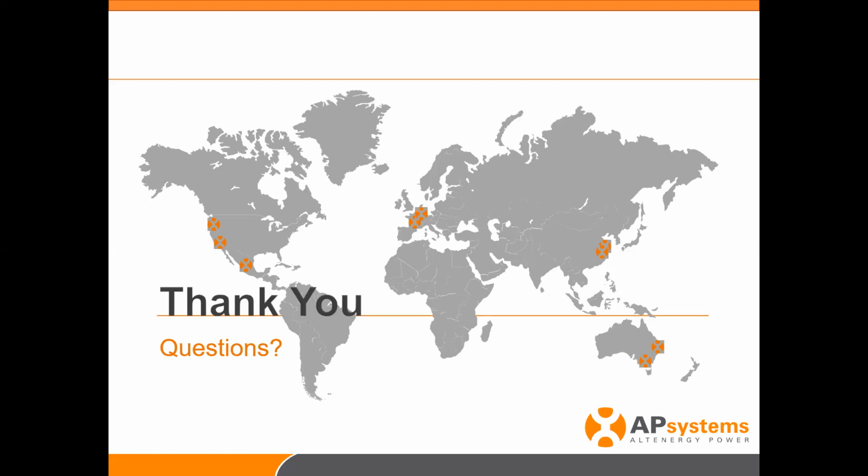So in 2017, NEC made it even worse by saying, okay, now it's not just bedrooms, it's all living spaces. So now the ECU that was located somewhere in a living room is now protected by an arc fault breaker. So we at APsystems made the conscious decision to change from PLC, power line communication, to Zigbee communication to avoid this arc fault breaker issue. And in doing so, we've actually made it so much better for you and for us.